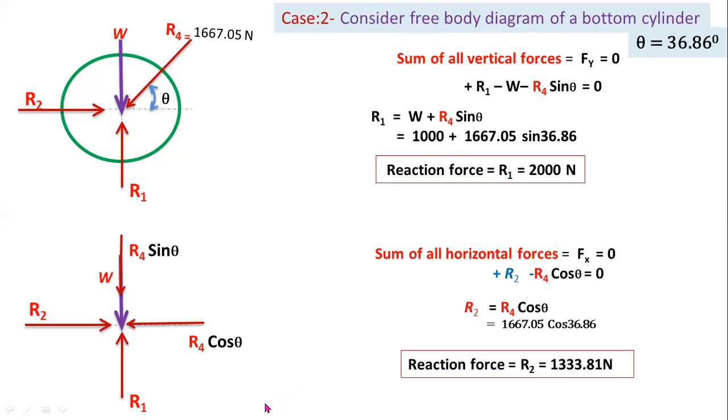Okay, friends. First of all, you have to convert the given diagram into a free body diagram. After that, you have to apply Lamy's theorem or another method for determining the unknown forces. In the next class, I will explain more problems on these equilibrium conditions. Okay, thank you.